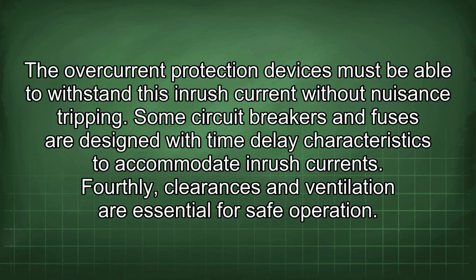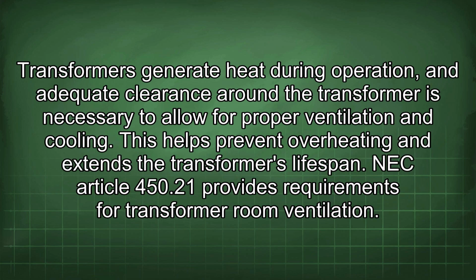Fourthly, clearances and ventilation are essential for safe operation. Transformers generate heat during operation, and adequate clearance around the transformer is necessary to allow for proper ventilation and cooling. This helps prevent overheating and extends the transformer's lifespan. NEC Article 450.21 provides requirements for transformer room ventilation.